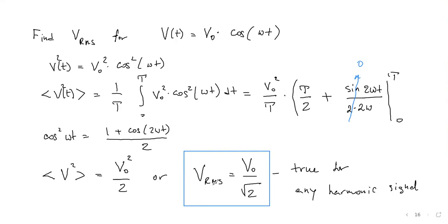So then you never talk about peak values unless there is a separate statement that this is a peak value. You always assume that you are working with RMS or average value. And when you say 120 over 60 is my power supply, then this 120 volt is actually the RMS value.